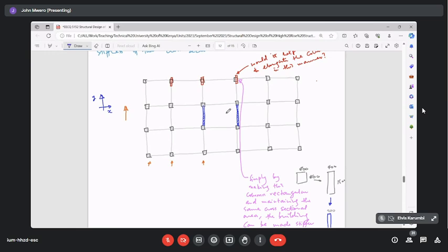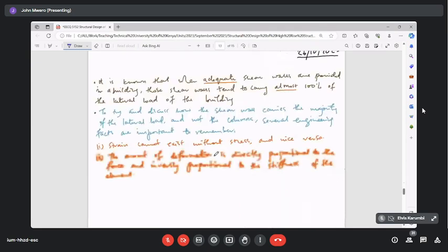So if you're doing hand calculations, you don't need to bog yourself down with too much calculation when you are almost sure that almost 100% of the loading will, either way, go into those shear walls. So it just makes sense to take this truth as it is, and to just load the shear walls with lateral loads, and then the rest of the vertical elements, that is columns, will carry the gravity loads.